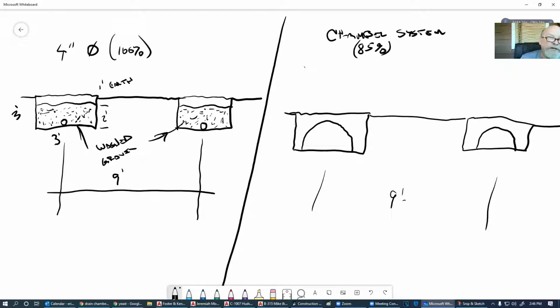One cubic yard of washed stone is equal to almost 1.5 tons. We're on a slope, it may have snowed, may be rainy. The ground outside today at my house is still kind of mushy. So I've got to get a dump truck up here so that I can put this gravel in, or I'm going to end up running a hole in the yard with the excavator or the bobcat going back and forth between the dump truck and these trenches.